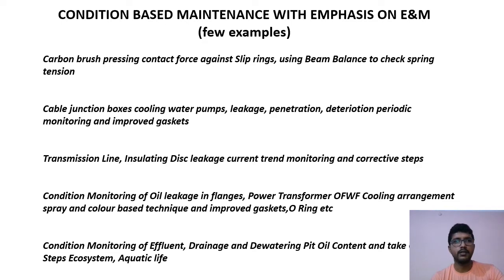Also deterioration of the equipments, and we also know that we have transformer condition-based maintenance packages for transformers like dissolved gas analysis and oil PPM and BDV. These are the smaller examples which are normally overlooked, but it matters a lot, right?